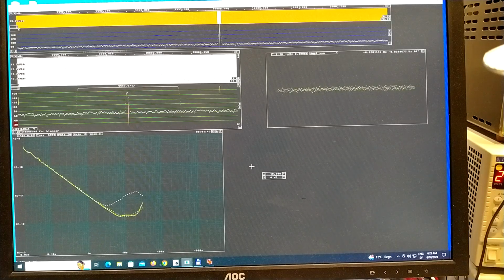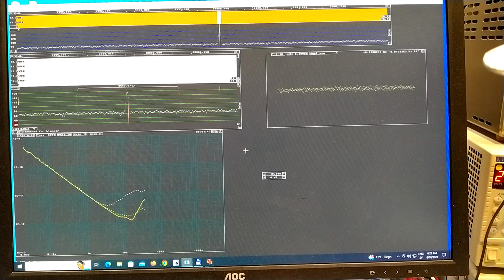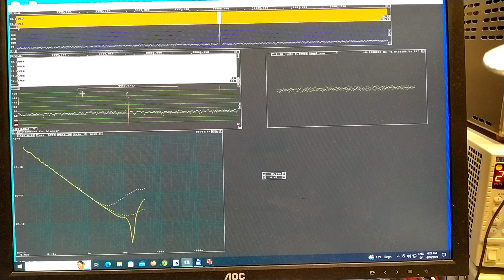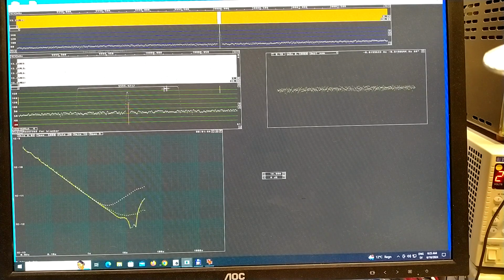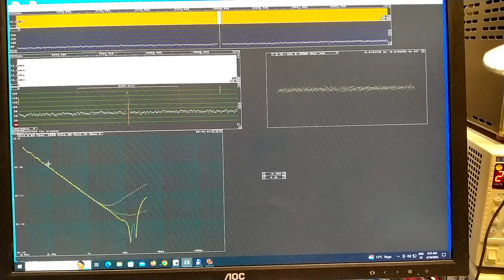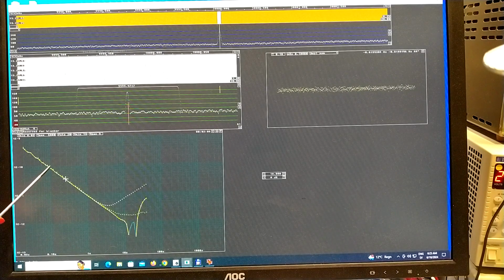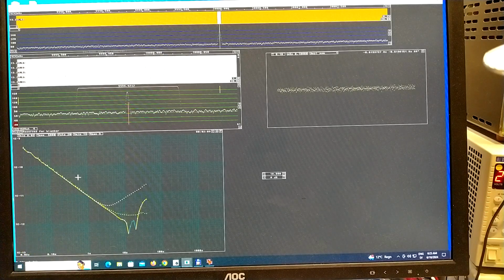In Linrad, I have another kind of filter before the Allan evaluation. It is the baseband filter. If it is wide open like this and with a very strong flat noise floor, I get this curve that slopes with a theoretical factor of 10 for a factor of 10 in frequency.